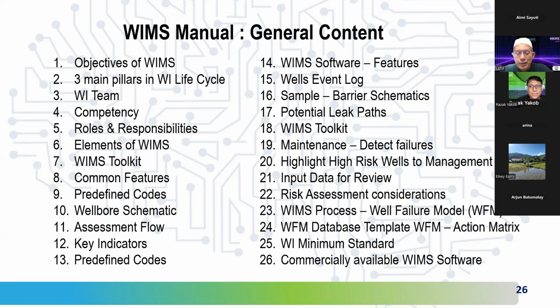So we try to see some areas, they record some of the life of, for example, the wing of the gate valve. Normally, after a certain rotation, they see the potential failure of the gate, and then of course some of the, for example, triple SV, after doing some manipulation of the valve, they start to see indication of failure after the 20th test or cycle and so on. So it's all the key indicators on the key elements in the completion string itself.